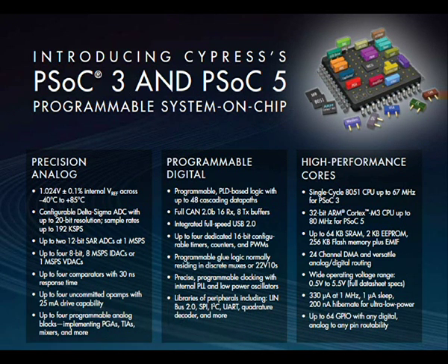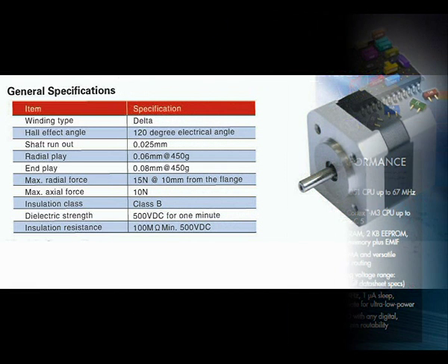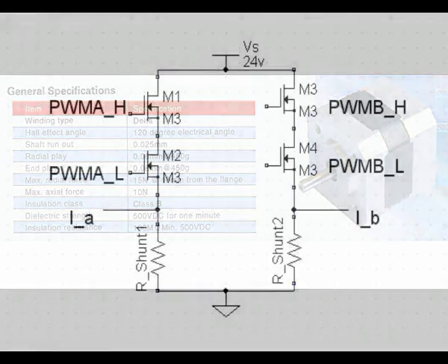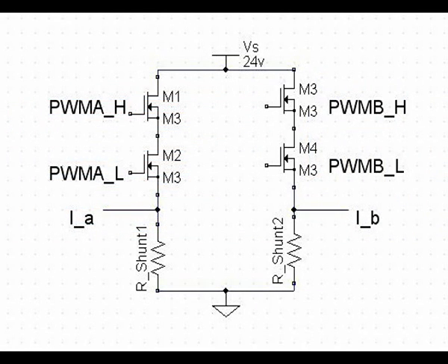The motor which is being driven in this demo is an 8-pole 26-watt BLDC motor. The algorithm we have implemented can drive any permanent magnet synchronous motor, or PMSM for short, or a brushless direct current motor, or BLDC for short. The only modification required is to have the appropriate driver board that can support the wattage rating of the motor and an appropriate two-phase current measurement circuit to measure the maximum current consumed by the motor.